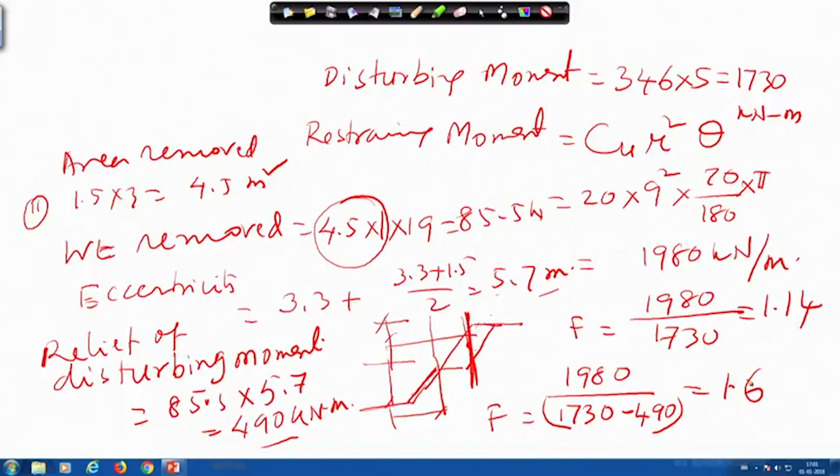When there is a slope and we find that it can be unstable any time, to make the slope stable we can cut some portion from the top. Or sometimes, if we have a steep slope, instead of making a simple slope, we can make a benching. That means, this is the one. So, we can do small benching.